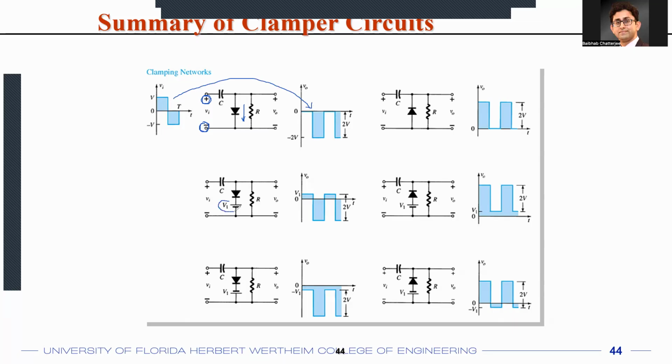Now, if you had a bias voltage like this, and again, this is the scenario when you have the positive polarity on the top side and the negative polarity on the bottom side. So when you do not have any input, even in that case, you basically have this plus 10 volts. Or this point gets mapped to the plus 10 volts. Similarly, if you flip the polarity, you'll go to minus 10 volt over here. And then this is 2 times the original amplitude of the voltage.